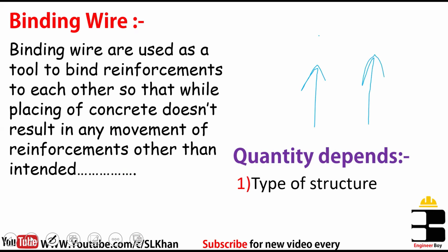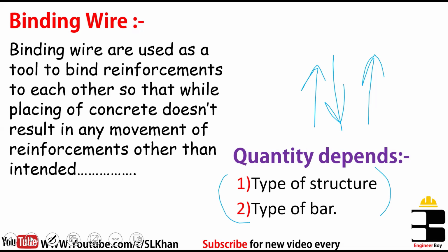And if the bar's diameter is actually more, then the quantity may decrease, because with a huge diameter, the bar may stay in place and there may not be any requirement of the binding wire. So it actually depends on these two parameters. Okay, now let's have an example so we can understand the calculation process for the binding wire.